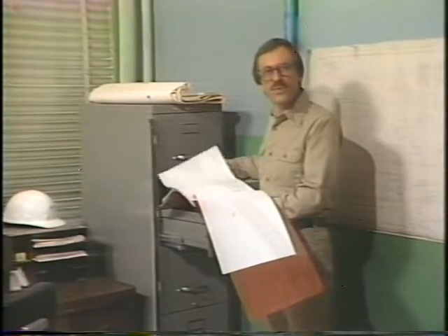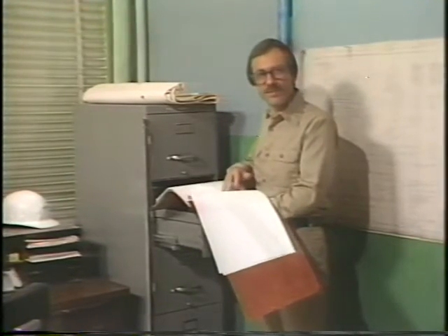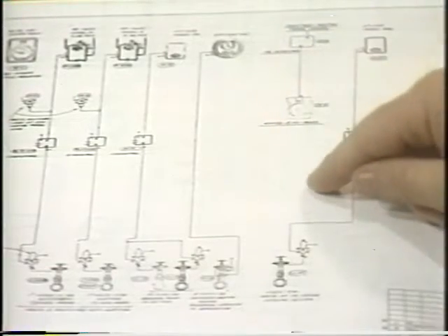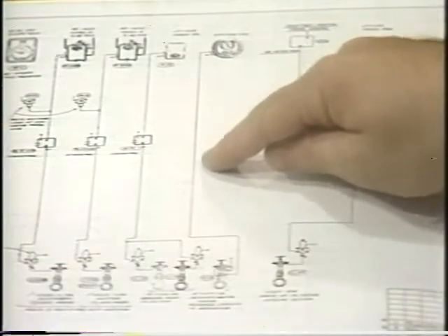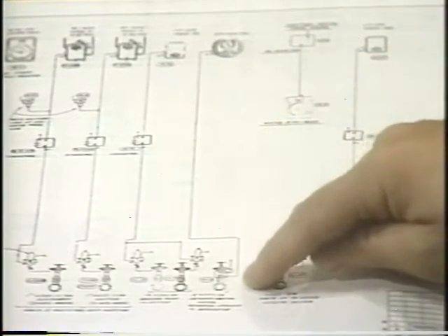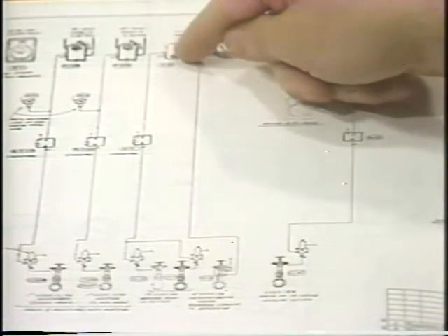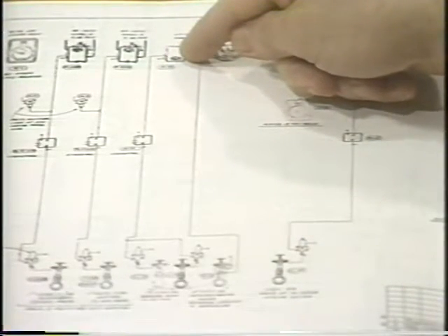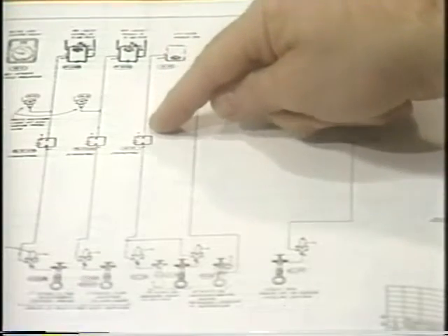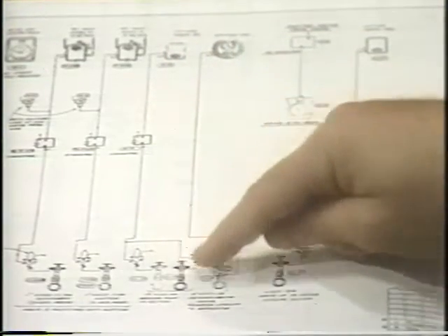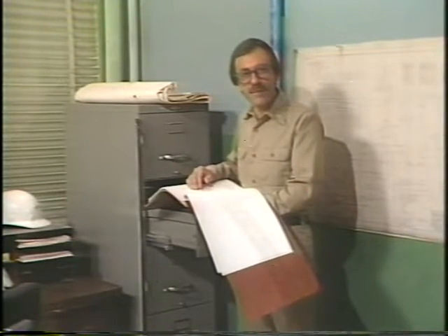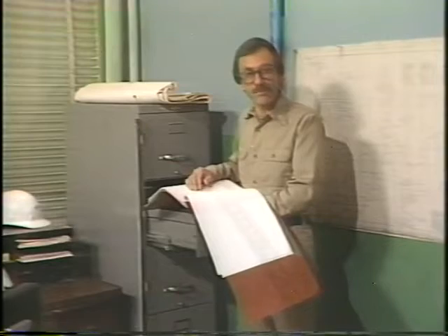Now, another source of information that's often a lot of help is a control logic diagram. It shows the progression of control signals through the control instruments in a system. It usually starts with the first element in a system, the primary measuring element, and continues through to the last element, usually the final control element. Using a combination of P&IDs and control logic diagrams helps you to get an idea of the instrumentation contained in a particular system so that you can locate the problem.